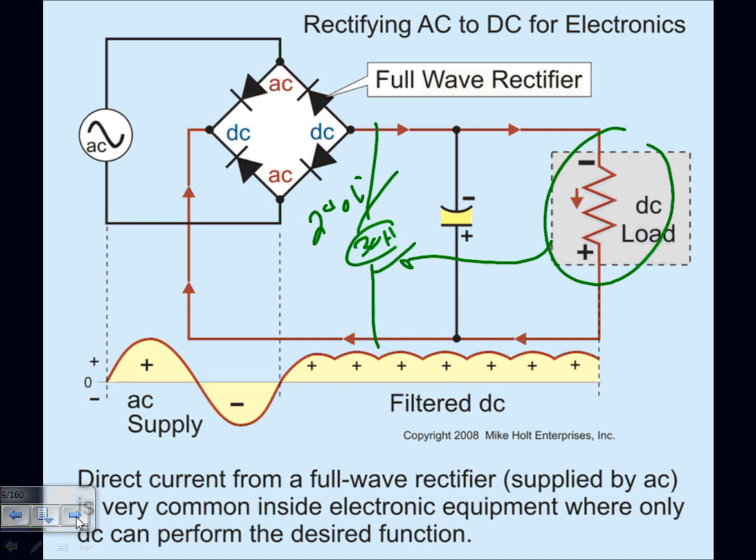Full rectification. The advantage of these DC motors, guys, is they're still more robust. Speed control is great for them. For conveyors and so forth, they use them a lot. And how do you get a DC motor to run a conveyor? No problem. Take an AC circuit, bring in a DC drive, so you can convert it to DC at the right voltage, and dump it across the coils of the motor. So that's the conversion, guys, and I'm not going to go through it, I've done that. You smooth it a little bit, and you've got yourself a DC.